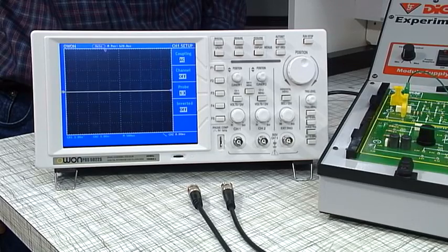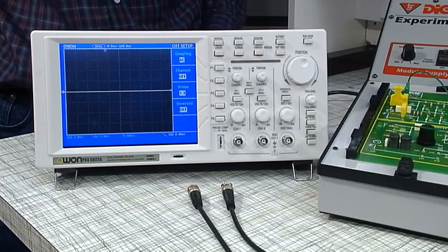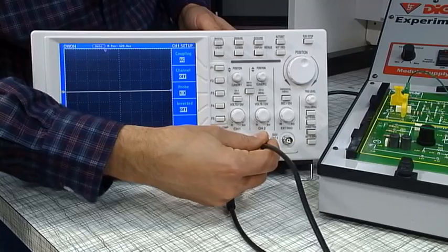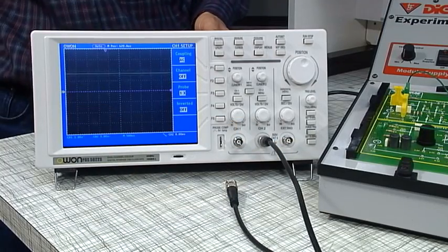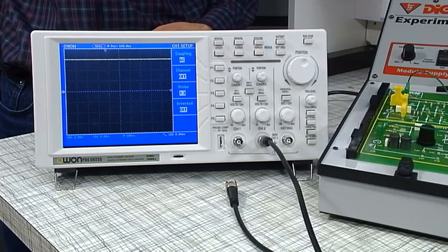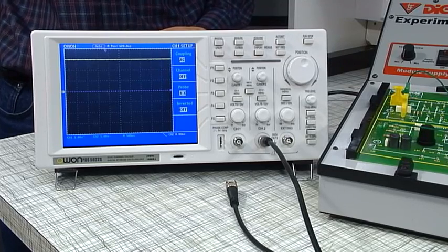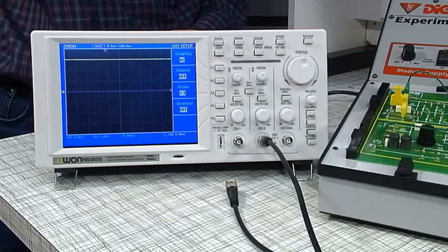Oscilloscopes can also be used to measure DC voltages. Unlike AC signals, a DC signal has no time variation. Therefore, when a DC voltage is displayed on an oscilloscope, the traced line is displaced from its reference point by the value of the voltage.